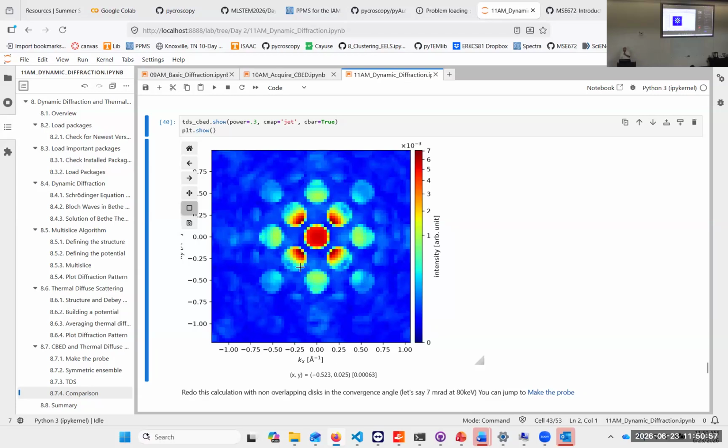You can see it is a fourfold symmetry of the diffraction pattern. When the Kikuchi bands overlap, you will see them in all directions. Again, very, very sensitive to any kind of tilt or deformation, since that will redistribute.